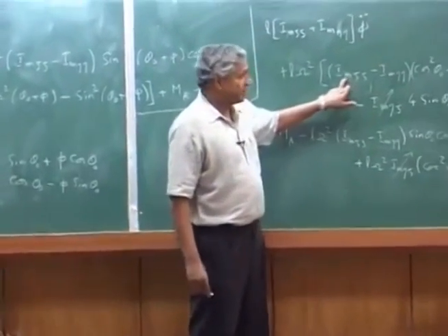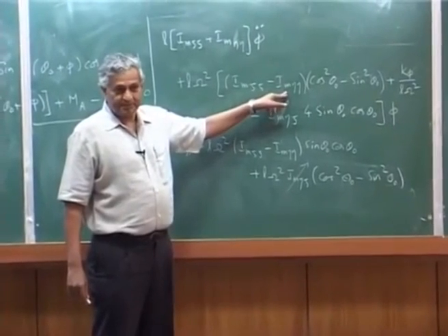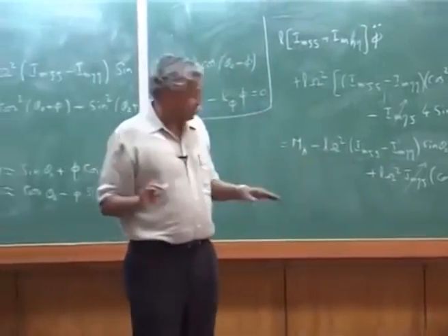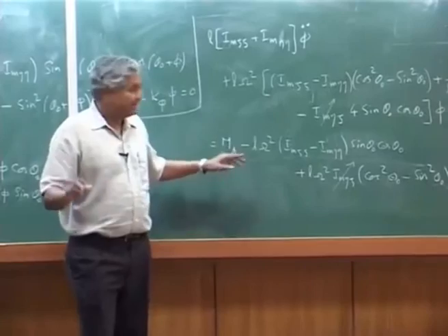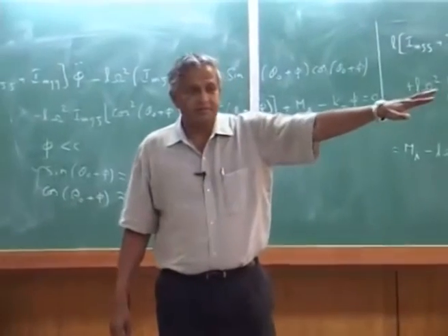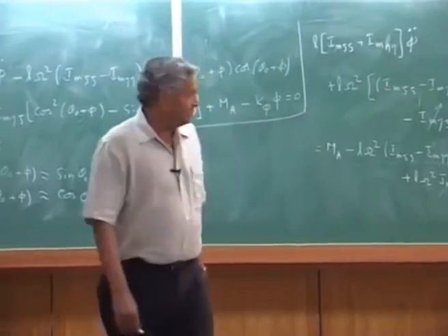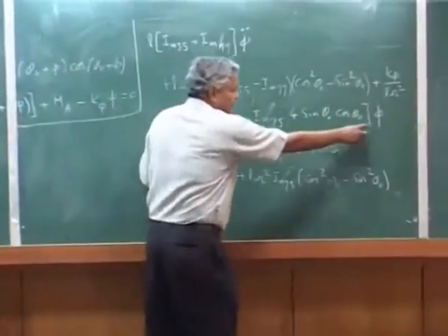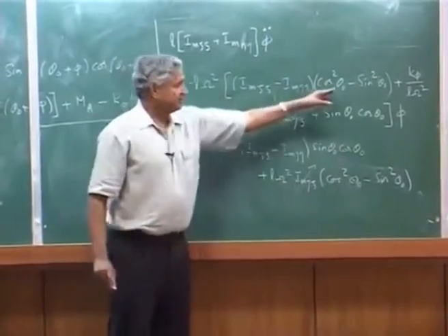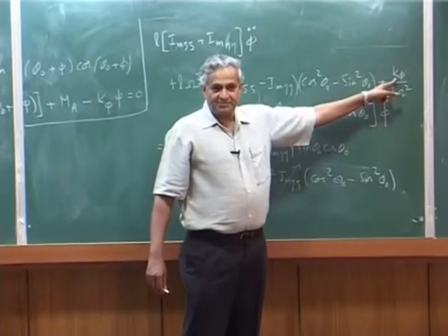And even this quantity is larger than this quantity. You will find without dynamics, in the sense without any external aerodynamic loads, there is no phi double dot, the equilibrium torsional deformation of the blade, phi equilibrium, equals this quantity divided by this quantity, and that depends on the torsional stiffness.